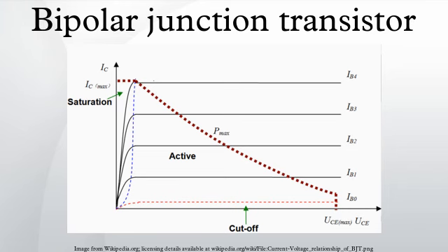Active mode NPN transistors in circuits. The diagram shows a schematic representation of an NPN transistor connected to two voltage sources. To make the transistor conduct appreciable current from C to E, VBE must be above a minimum value sometimes referred to as the cut-in voltage. The cut-in voltage is usually about 650 mV for silicon BJTs at room temperature but can be different depending on the type of transistor and its biasing.